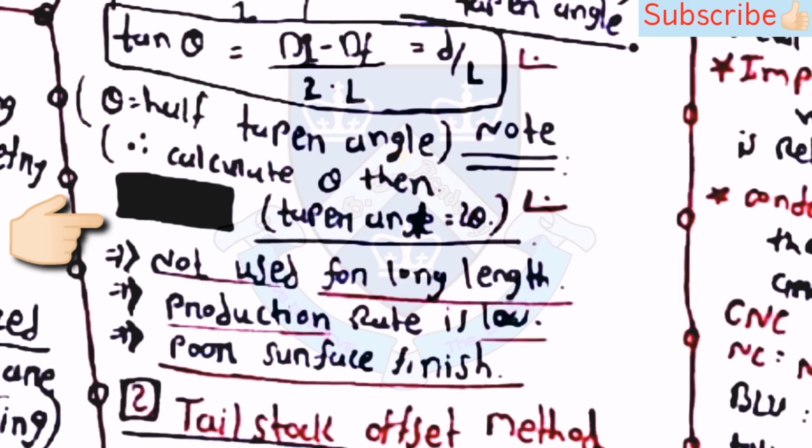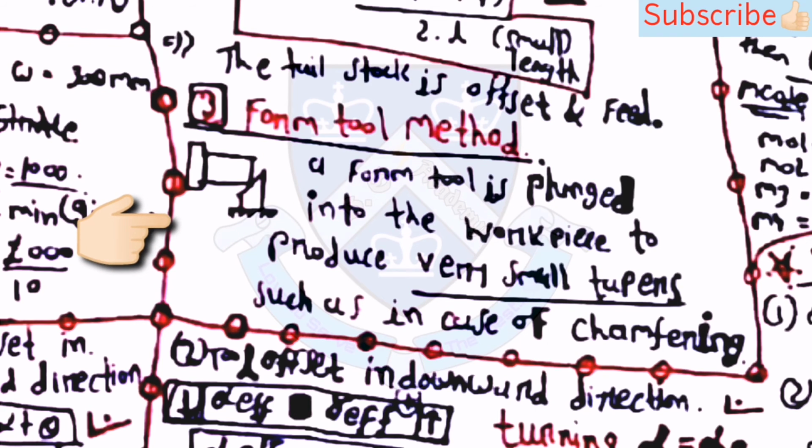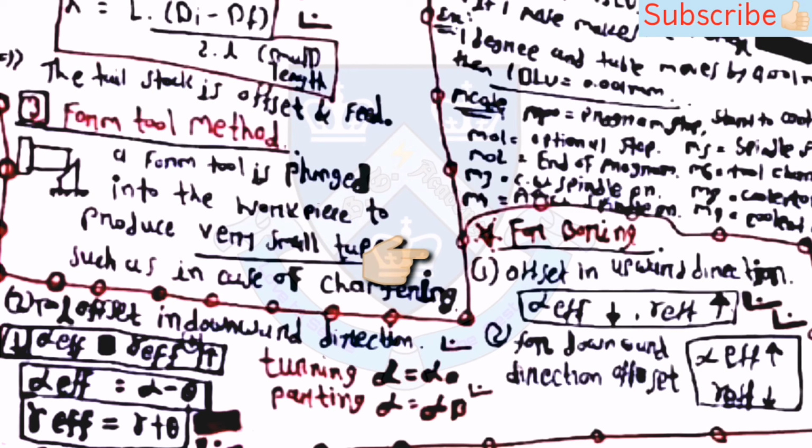And it is not used for long lengths, and the production rate is lower and the surface finish is poor in the compound rest method. Then in the tailstock offset method, h is equal to l into tan theta, and h is equal to l into di minus df by 2 into l. Then the tailstock is offset and fed. Then the last one is the form tool method. In this method, a form tool is plunged into the workpiece to produce a very small taper, such as in case of chamfering. Now these are some notes for the boring process.